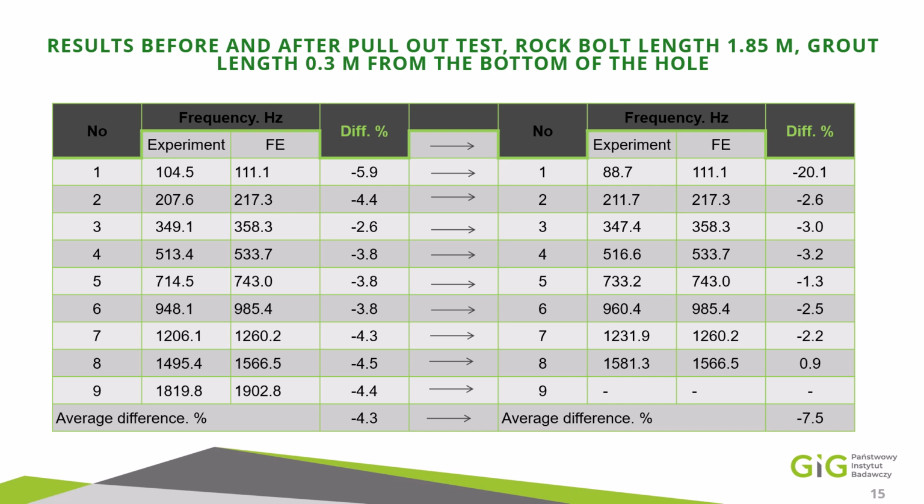Also, the measurements were performed before and after this pull-out test, so also kind of checking this accuracy and repeatability. Certain shifts in frequencies were observed, especially in the highest frequency, probably an increase in stiffness after the pull-out test.